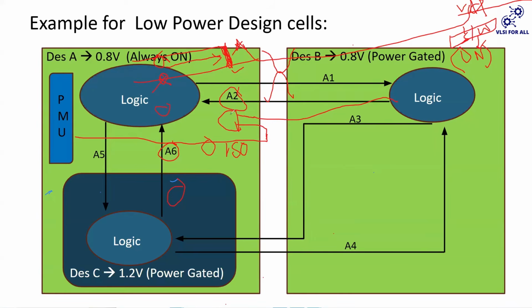See, when you are looking at a cell, you always forget that it always has power and ground pins. It has VDD and ground as well. Now, since this is an always-on domain, it will get the power, correct? But for example, if by mistake, I know that this signal needs an isolation cell, but I place this cell over here.